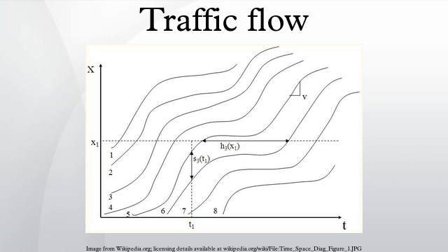The goal of Lighthill and Whitham, on the other hand, was to propose a new method of study suggested by theories of the flow about supersonic projectiles and of flood movement in rivers. The resulting model would capture both of the aforementioned relationships, speed-flow and speed-headway, into a single curve, which would sum up all the properties of a stretch of road which are relevant to its ability to handle the flow of congested traffic. The model they presented related traffic flow to concentration.